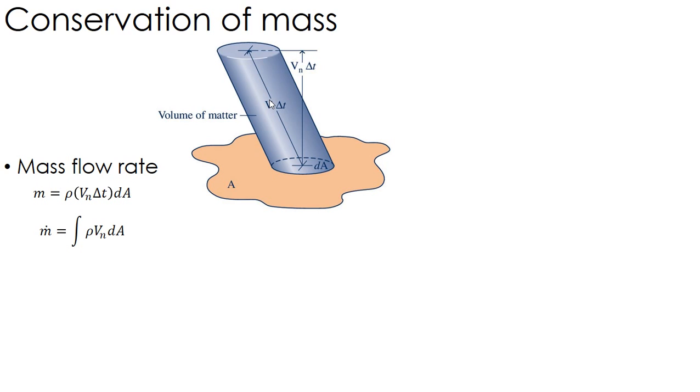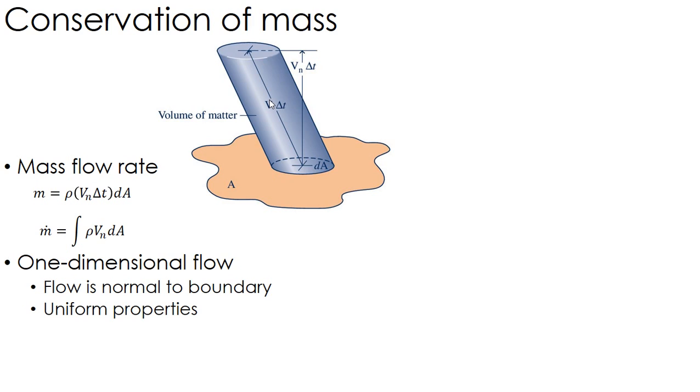Now, moving delta T over with mass, we get what's called mass flow: dm/dt, which is rho times the normal velocity times the area through which it passes. This is what we call our mass flow. Again, mass flow is the time rate of change of mass, dm/dt.